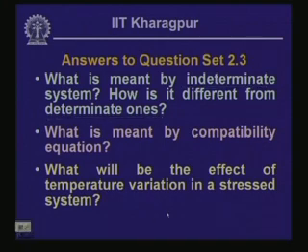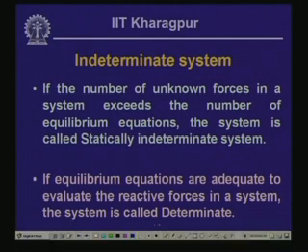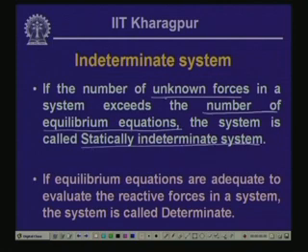Well, in an indeterminate system, the number of unknown forces are more than the number of equilibrium equations available, and those kind of systems we generally call statically indeterminate systems, where the number of unknown forces are more than the number of equilibrium equations.